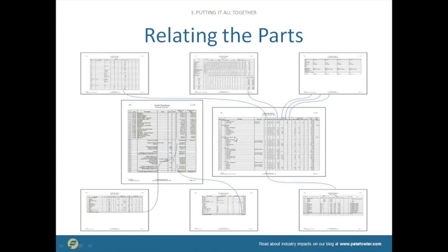And then there's the estimate details, which could be very, very long, because each line item on the estimate summary is going to be broken down into tremendous detail in the estimate details, if it's a detailed estimate. But the estimate summary sheet is also where all these other things come together. We've got a general conditions sheet down here that goes onto the summary page. Here we've got a relocation page, so if you're going to relocate somebody, it goes onto the summary page.